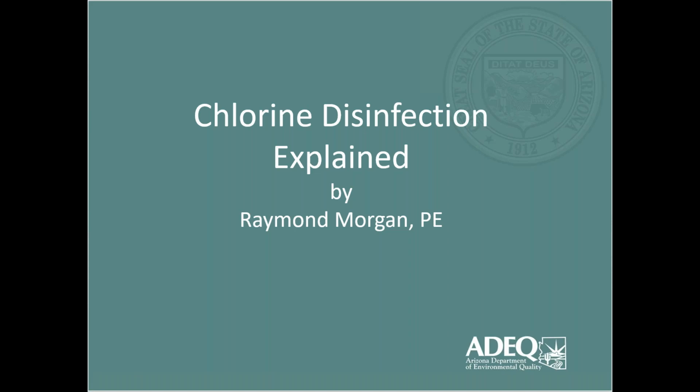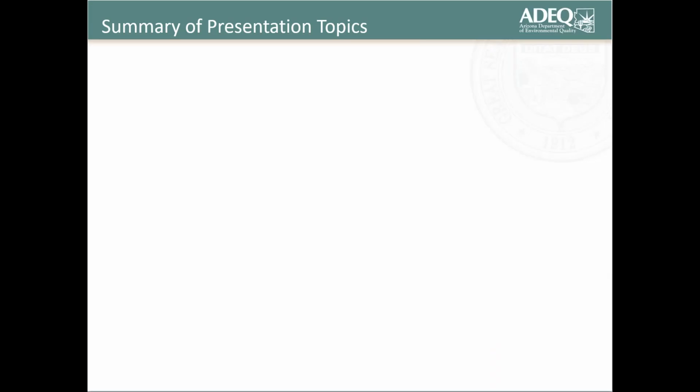We're going to look at some key terms and what those mean. Then we're going to look at another presentation. We're going to do some calculations, calculate the detention time. And then we're also going to look at an Excel spreadsheet that's been developed to allow you to calculate the number of tablets that might be consumed, associated with a given flow and a given disinfection dose. So with that, let's take a look at a summary of the various presentation topics that I want to try to cover today.